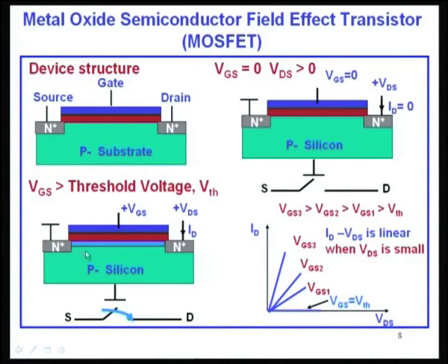But if there is a drop of half volt between the drain and the source, the voltage available for creating this charge changes. The applied voltage is 2 volts, I require at least 1 volt to create the initial charge, so the voltage available here is 1 volt. So, 1 volt into capacitance is the charge here.